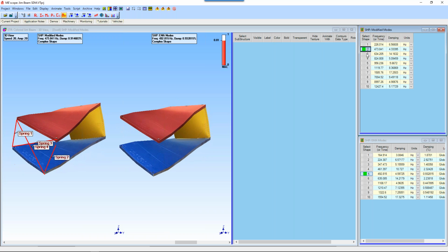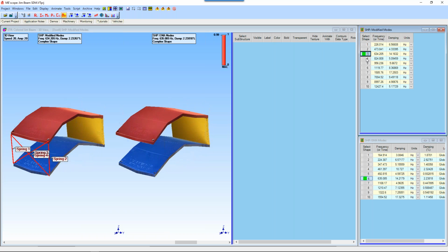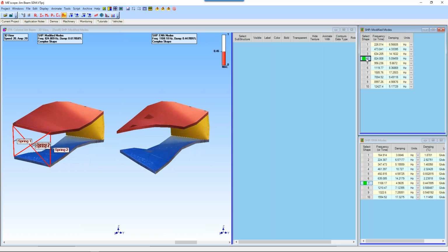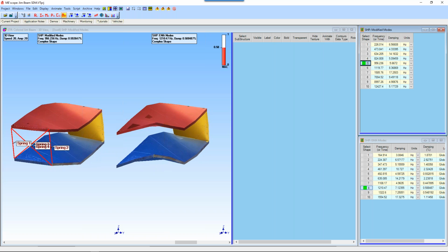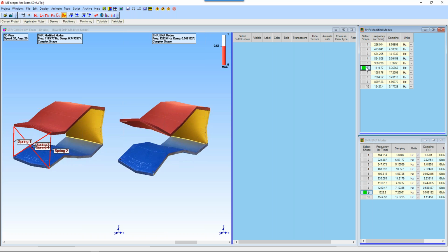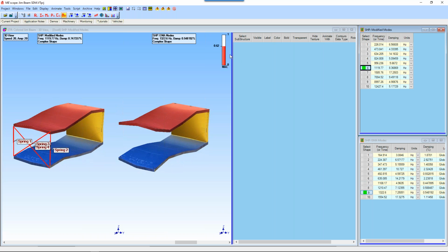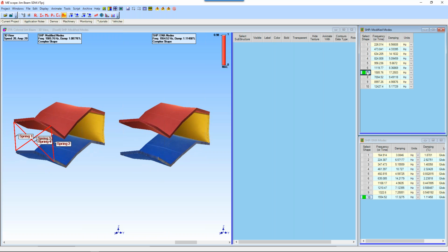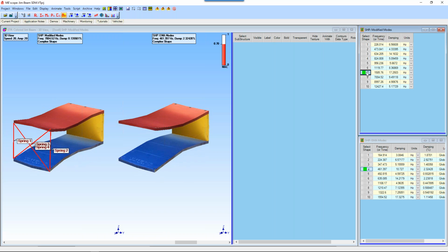And as I walk through here, you can see that mode was there. That mode also was in the unmodified structure. There's a brand new mode. Doesn't correlate much with anything. There's a new mode. So putting 4 springs on, there's another new mode. I'm looking here at the MAC values. They're very low. It doesn't correlate with anything. That mode is still around. Correlates very well, the 1500.